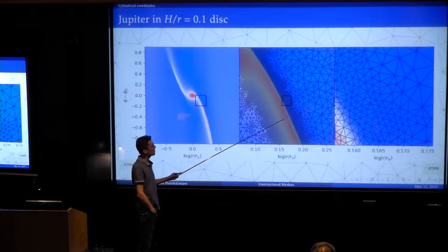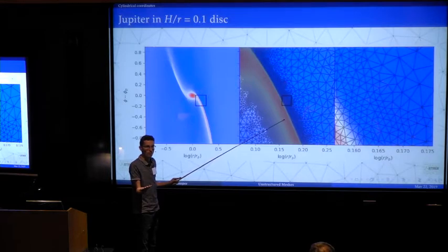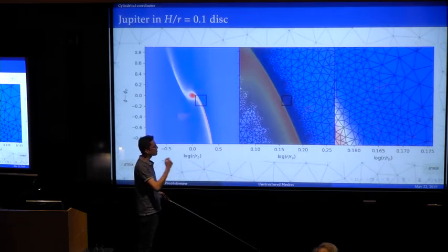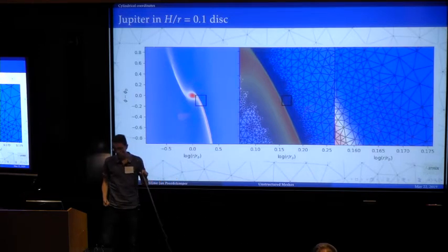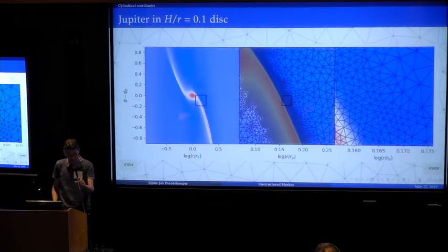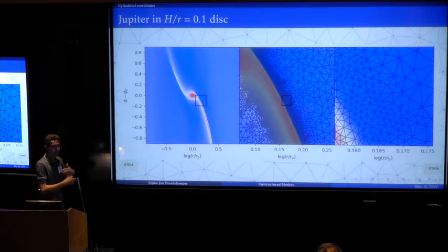But what you do is add points if necessary, and you can also remove points if you don't want them anymore. But they don't have any velocity themselves. And so this comes back to the quality of the mesh. That way we can guarantee that the mesh doesn't become distorted. This is one of the reasons I'm not a big fan of moving these things around.